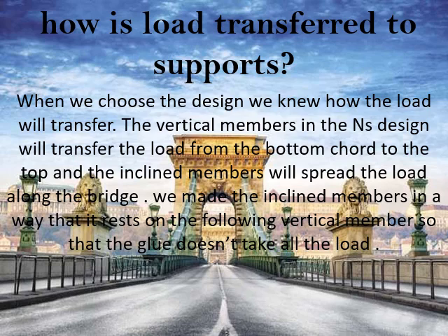The vertical members in the ends design transfer the load from the bottom chord to the top, and the inclined members spread the load along the bridge. So we made the inclined members in a way that they rest on the following vertical members, so we notice that the glue doesn't take all the load.